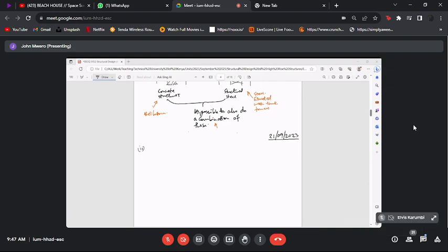Is a structural system that is generally referred to as a tube-in-tube. In this system, you have generally a central core or centrally placed reinforced concrete solid wall core, and then it is surrounded by columns. It's referred to as a tube-in-tube. For example, so let me just write here. This constitutes